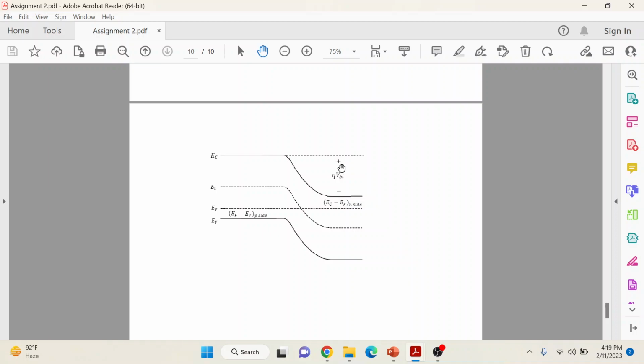Each material has some Fermi level, and we see how this Fermi level changes when we dope. Depending on this, we choose what material to dope and in which material we dope. So every material has some Fermi level energy. Are you getting me? Although this is not an experimental concept, there is a Fermi level where you can find electrons even at 0 Kelvin, and these are the electrons which are available and can decide the properties of your device. This concept is very important for devices like LEDs, transistors, photodetectors, solar cells. So we need to know the Fermi level energy.